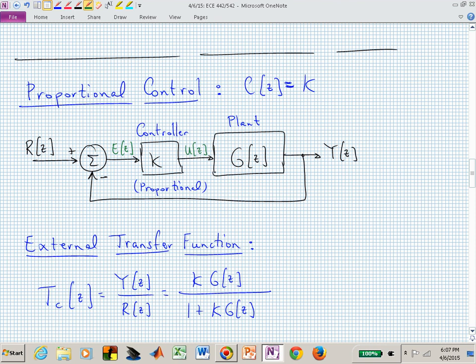You can put poles and zeros outside the unit circle. In earlier classes, I talked about having a pole shaker and a zero shaker, and you're now sprinkling those poles and zeros on your complex Z-plane to give you the behavior that you want.